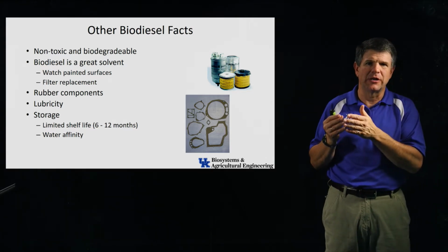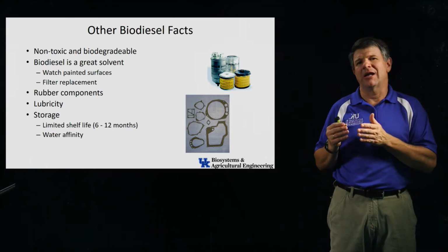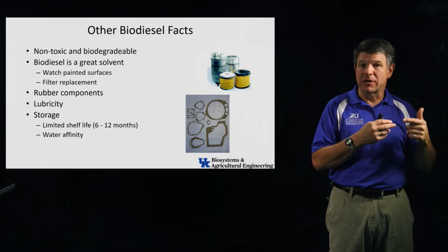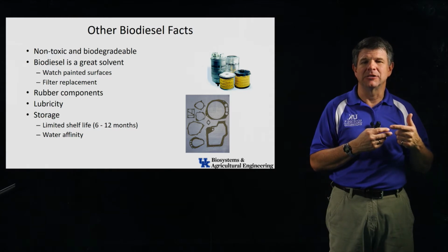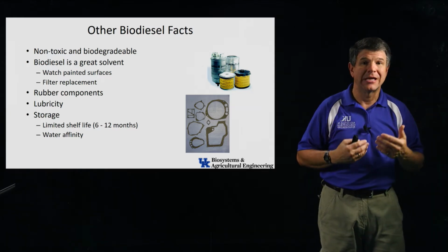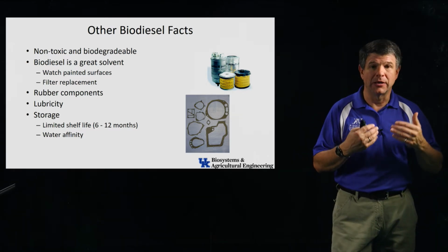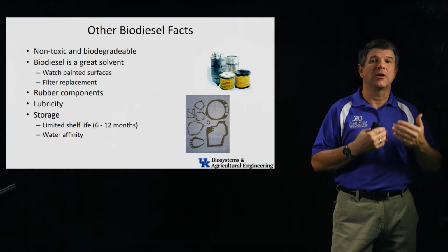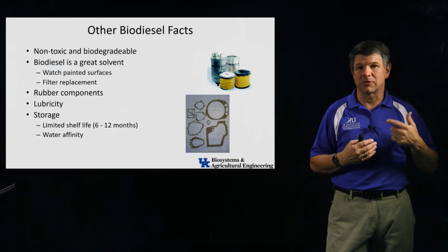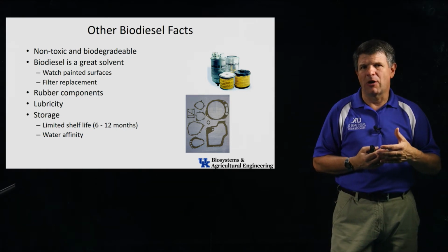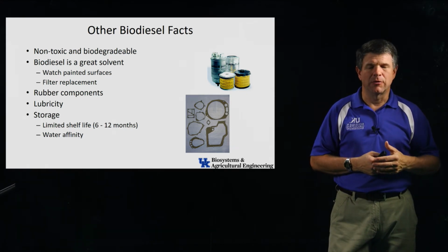If you look historically, diesel fuels had a lot of sulfur in them. The sulfur actually gave us the lubricity. It actually would lubricate the engines. And a number of years ago, for obvious environmental reasons, the fuel companies had to take that sulfur out of the fuel. So we had to go to a low sulfur diesel fuel. Well, then we lost all the lubricity. So the engines were starting to fail. So they had to find compounds that they could replace the sulfur with in the fuel to create the lubricity.